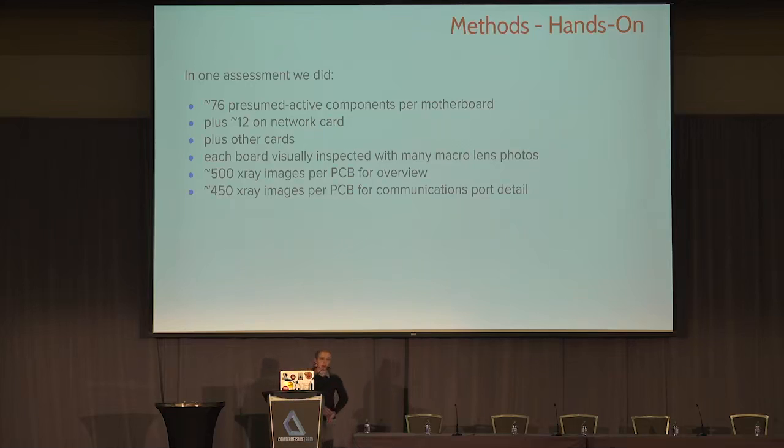So one idea that I think is kind of in research stages now is to actually use OpenCV or something like that to process all of these images of the board itself, so maybe pull off that net list, or of these X-rays to pull off the different interconnects between the layers, and maybe match that against a known good PCB X-ray.